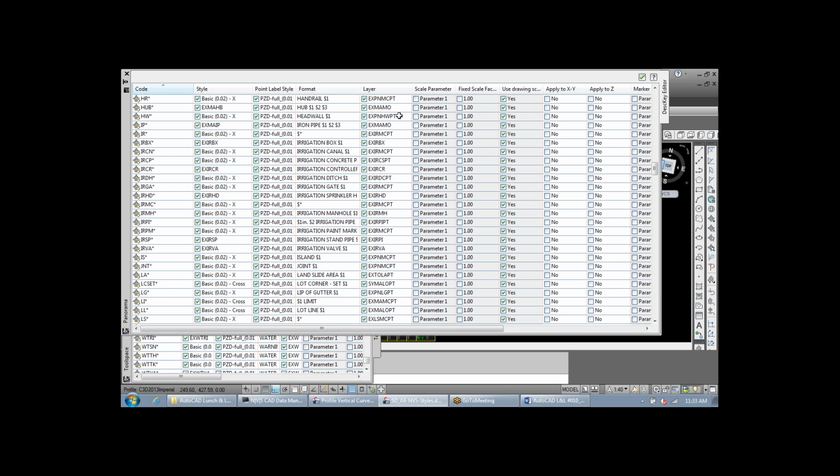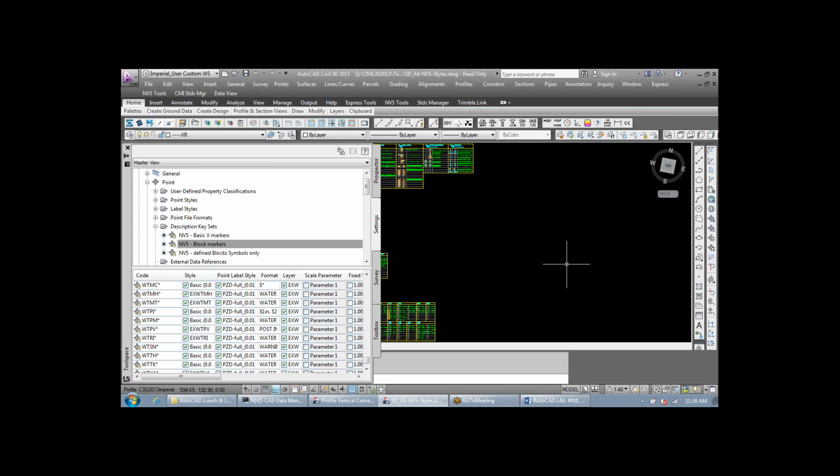Now what happens is somebody makes a change to the alignment, and all your labels that you just spent a couple hours moving to clear, over 7.5 miles, the minute somebody changes that alignment and the data reference synchronizes, all those alignment labels snap back to their original location. And then you've got to redo all that text dragging for 7.5 miles. There is a solution. It's not an elegant one by any means, but it can save you from having to redrag all those texts for 7.5 miles, or however long your project is.